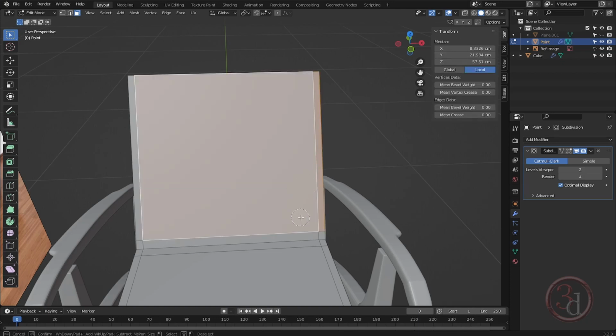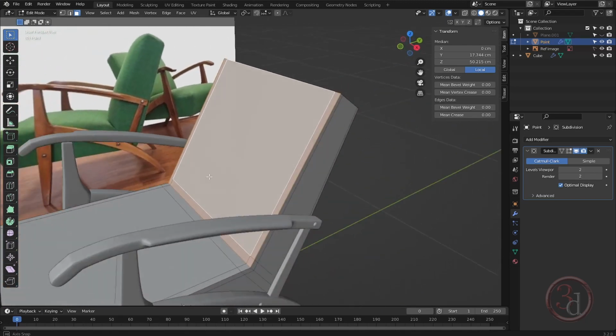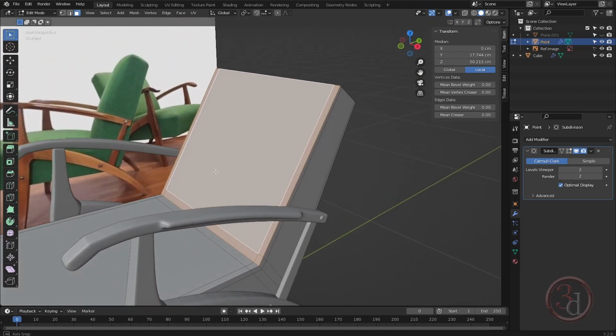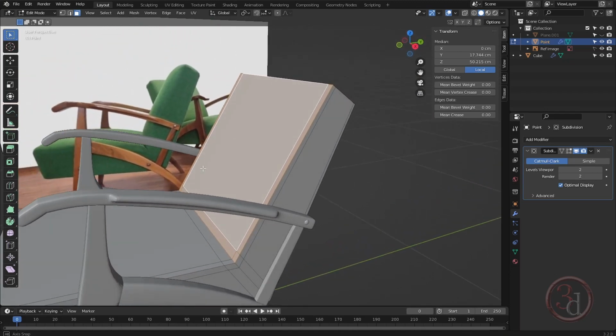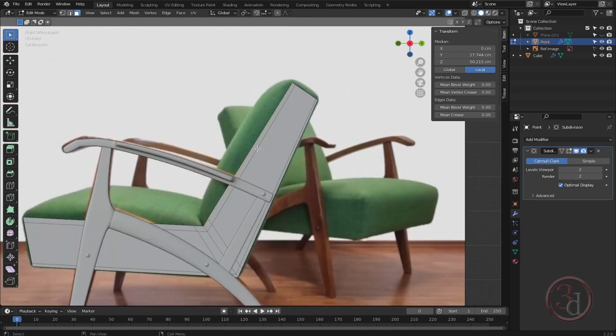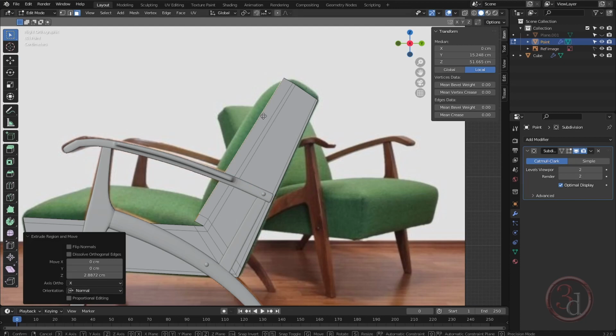It's like paint mode to select your faces, and it will add to the selection, and then you just press right click. So now you have the selection. Okay, so if I go to the right view and then press E to bring this out, and then press G to just adjust the extrude.